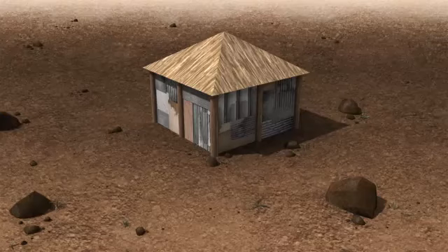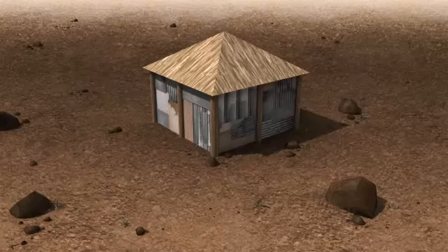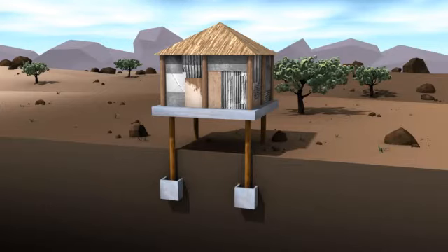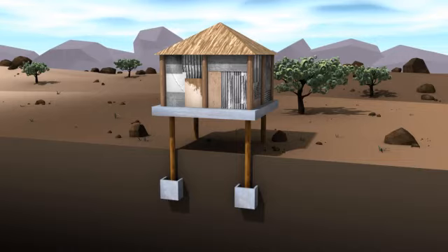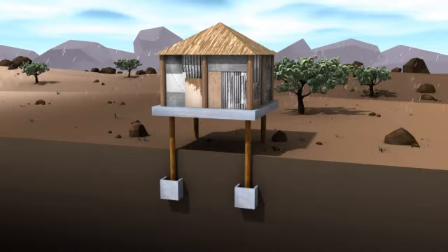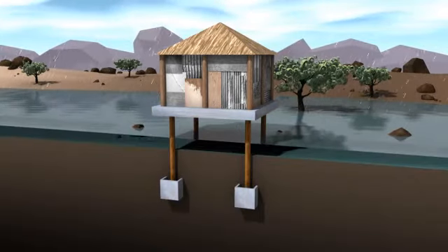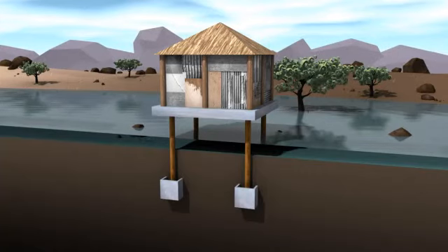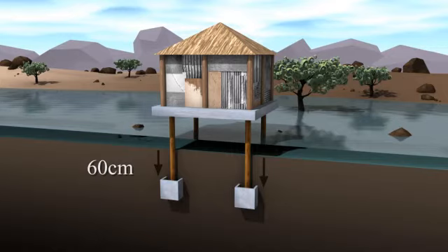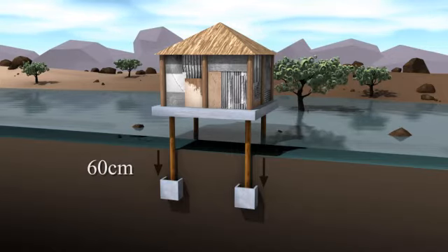Although it can be a lot of work to dig the foundation, it is still the most suitable for the construction of shelter. For increased stability, it is important that the shelter's foundation is deep enough to manage the weight of the building and to avoid potential collapse or damage. It is recommended to ensure that the top part of the foundation is a minimum of 60 centimeters below the ground level. The bottom part of the foundation, as well as its size, will depend on the size and weight